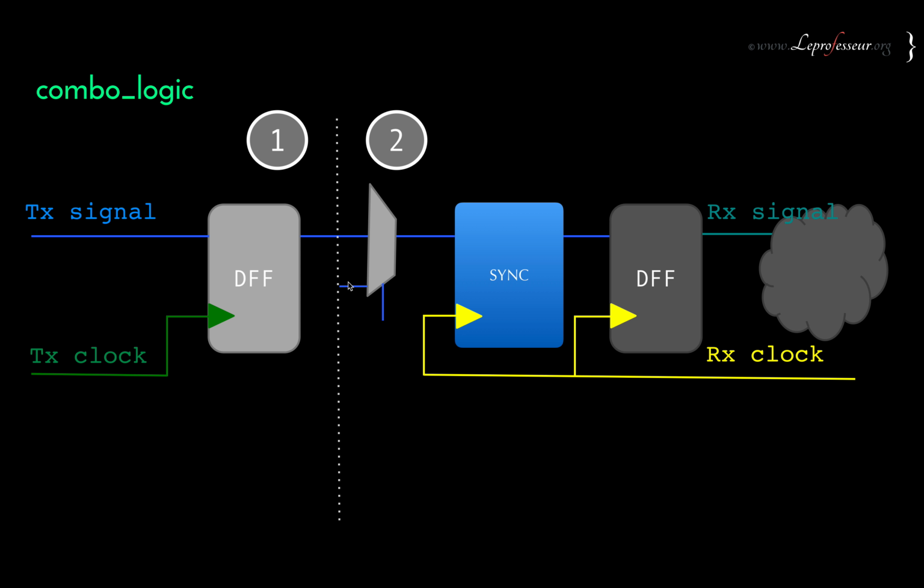Most of the time, the select signal is constant, and the other signal is constant if it is a test mux or a DFT related mux. But if it is not, then you have to be very, very careful that this signal should not be switching, and the other signal should not be switching. If both signals switch at the same time, we are toggling this signal too much, because we don't know at what time this signal will toggle.